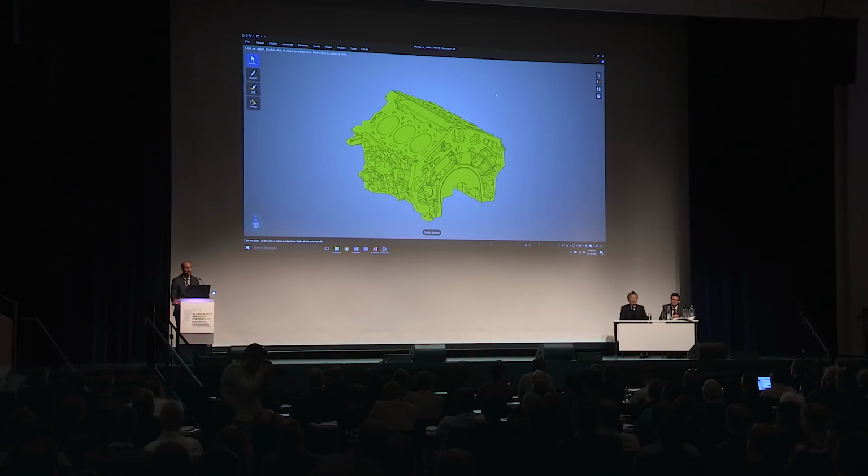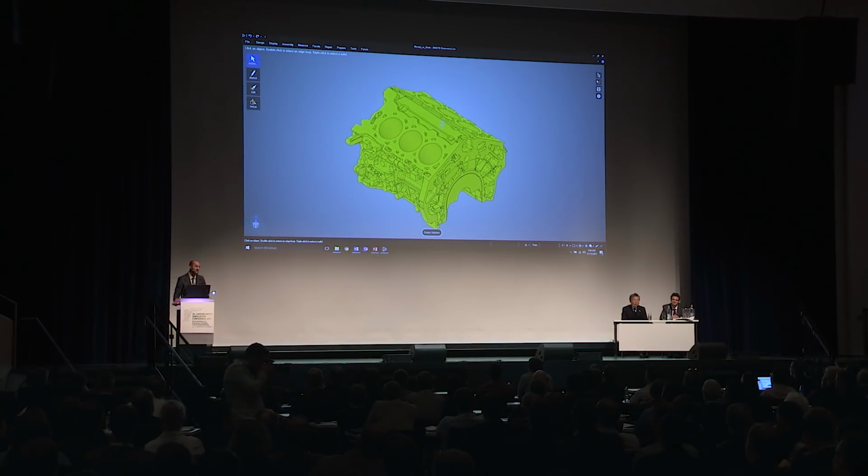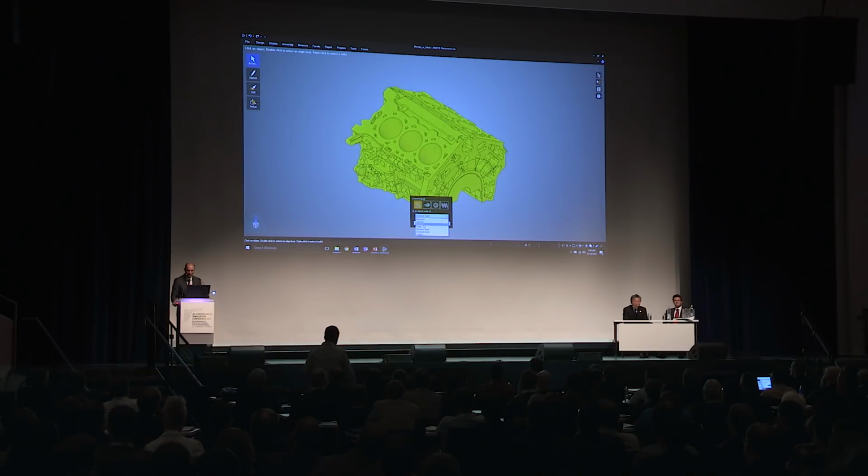So this example is big. There are 16,281 faces on this engine block that appear right here. Let's imagine that as a designer, I want to get a feel for how it behaves. So, ignoring this other one, let's pick the bottom that appears at the bottom and say, let's add physics, because we're always talking about adding physics. And we'll do a thermal study. We pick a material. Let's say this is a cast iron block, right?